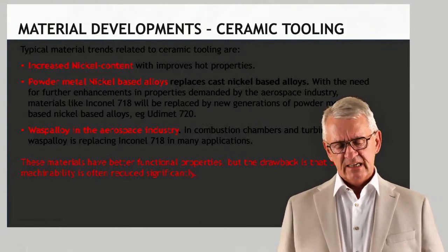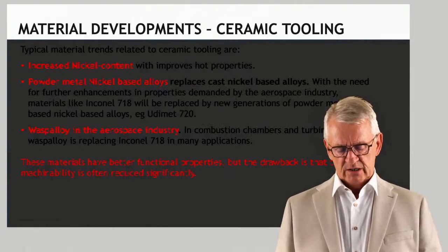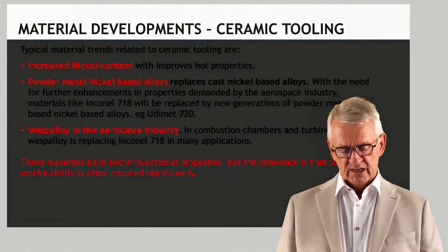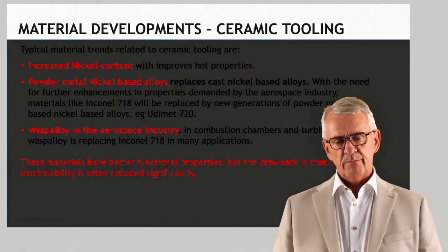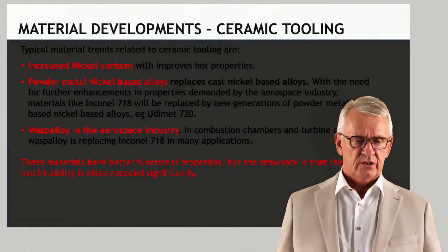So we see that, and in the meantime, I have been kind of defining what we call advanced cutting materials. It's PCBN materials, cubic boron nitride, it's PCD, it's diamonds, and it's ceramics. Those three kind of we call the advanced cutting materials.